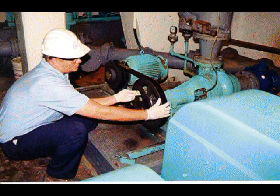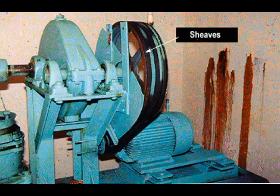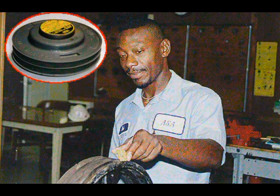To change the speed ratio between the pump and the motor, it is only necessary to change a pulley. Pulleys can easily be adjusted and aligned. V-belt drive pulleys are commonly known as sheaves. Normally, they are made of cast iron or steel and machined to size. Sheaves can be single-grooved, double-grooved, triple-grooved, or more if required to meet horsepower requirements of the system. It is important to periodically ensure that the sheaves are not becoming worn beyond the manufacturer's specifications.